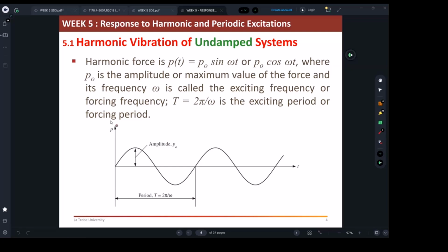Omega n comes from the nature of the structure. It is the natural frequency, right? Omega n. Tn was the natural time period. Today, we're talking about the excitations coming into the building. So the properties are written in the lecture notes and many textbooks just without any character. So omega means it's the forcing frequency. T is the forcing period. All right, so we agreed about this.